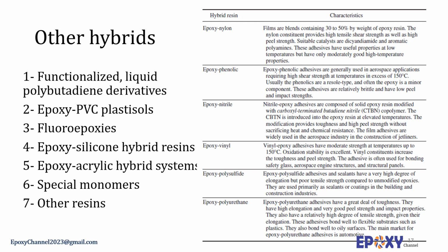Fluoroepoxies have gained interest because of the unique adhesion properties that can be provided by the fluorine group. In general, these have focused on adhesive systems that have a lower surface tension than unmodified epoxy or have significant hydrophobicity to resist exposure in moist environments.